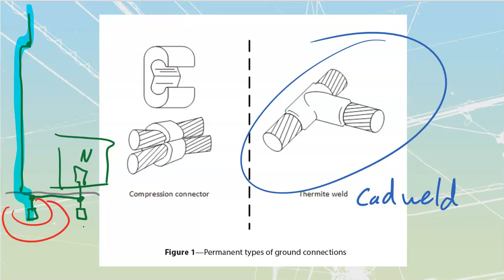Okay, so our 2 types of connections that are inside of there are valid types of connections. They're no longer required. They're still considered to be the best case type of connections. You can also use split bolts when you are connecting stuff together. But the problem with split bolts is that they have to be done up tight and they can be removed. Somebody all of a sudden decides that they want a couple ounces of pure copper to throw into the recycling fund. They just got to back that thing off, right? Those things go missing. These ones over here don't generally tend to do so.